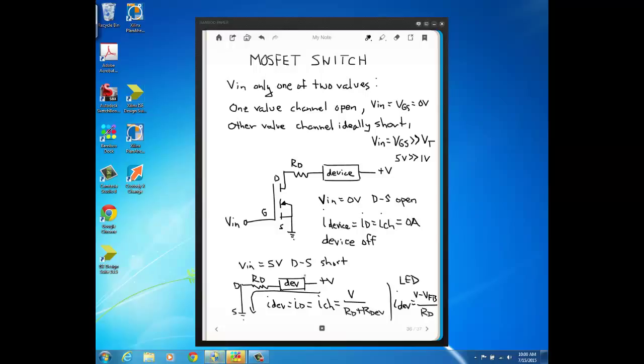In this class, if it's anything but an LED, you treat it just as a resistor, but if it's an LED or a diode, say a diode that doesn't give off light, you would treat it as a source of voltage drop equal to the forward bias voltage.